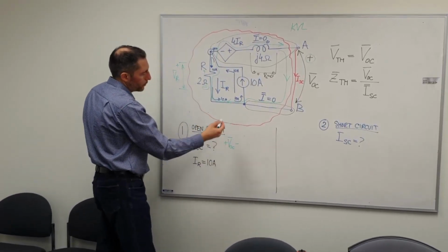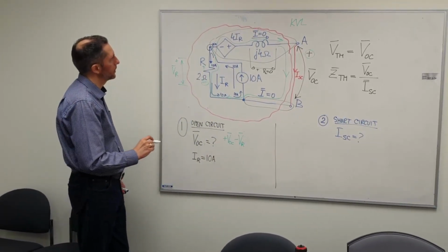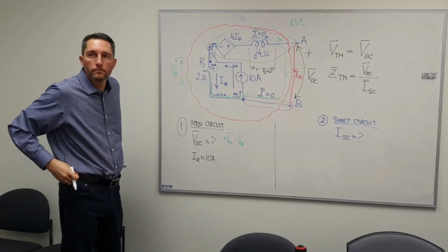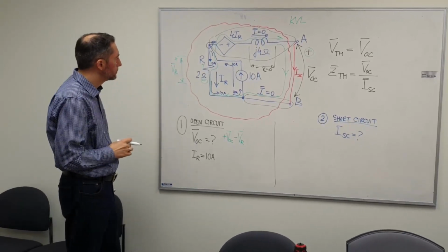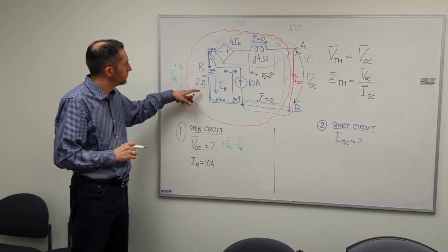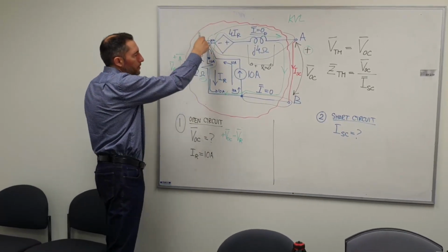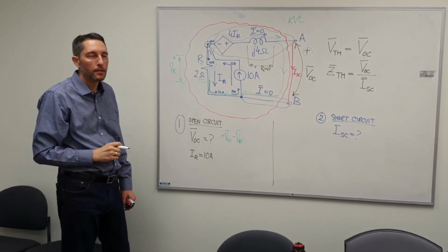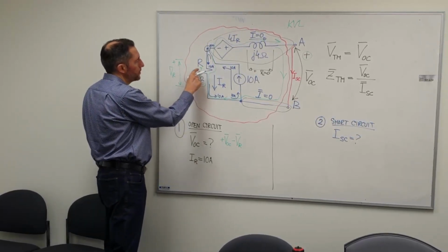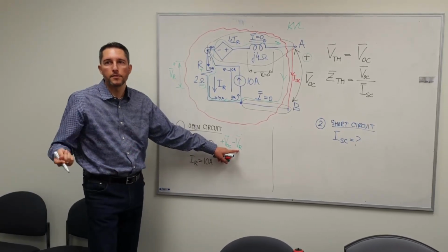Now, VR, let me write it as VR, and I'll deal with what VR is in the next line. So that's one. Sorry, Sasha. Would it not have made life so much easier for you to just write that down as a positive and then a negative? Where do you want me to put positive and negative? After the resistor. Is that because you're going to have a double negative? I normally like to put the positive for voltage where the current enters, so I don't end up with a negative in the Ohm's law. I could pick this to be positive and this to be negative, but then my VR will be negative current times resistance.